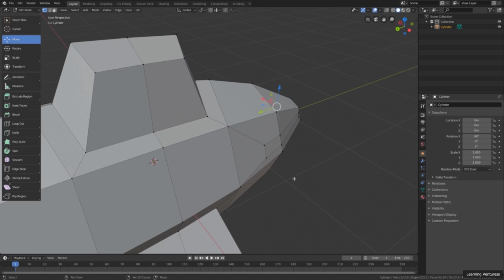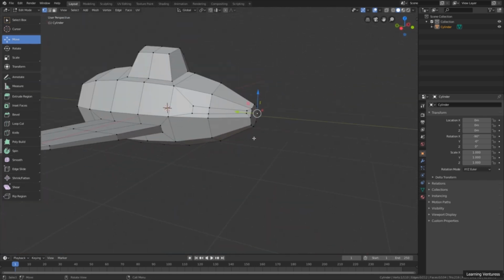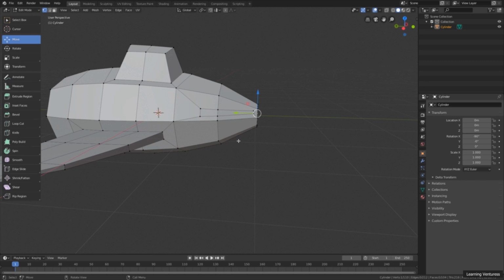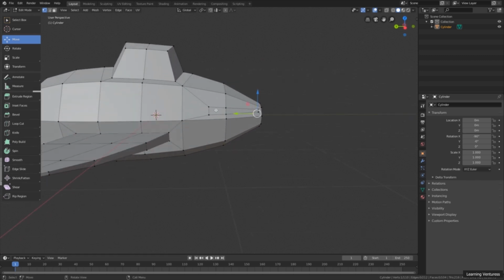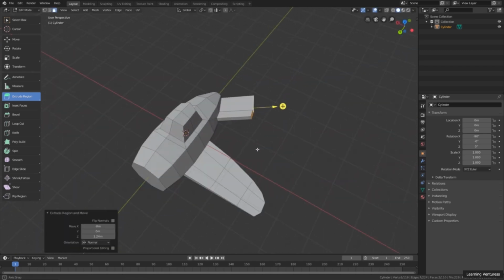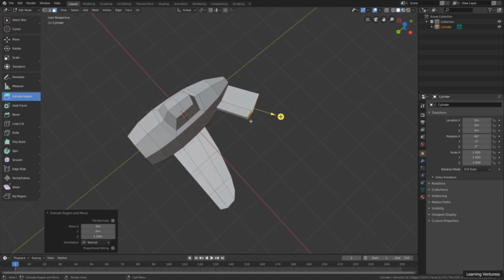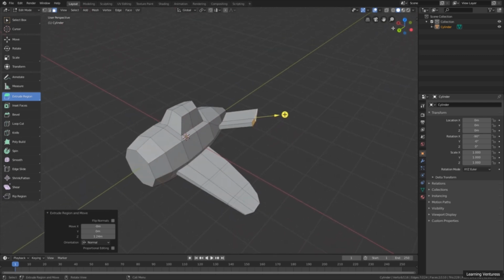And now I believe that I have a good pair of polygons here so that I can extrude my rear wing. Okay, so now I can activate the face selection mode again, select those two faces we just adjusted, and activate the extrude region tool and extrude these faces like this. As we have seen, the extrusion will follow the alignment of the original faces,